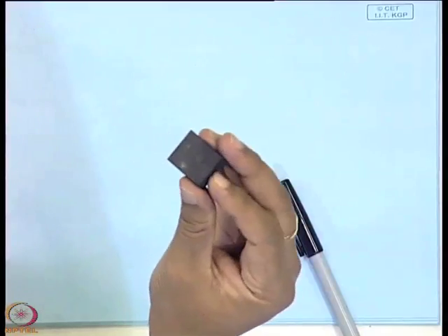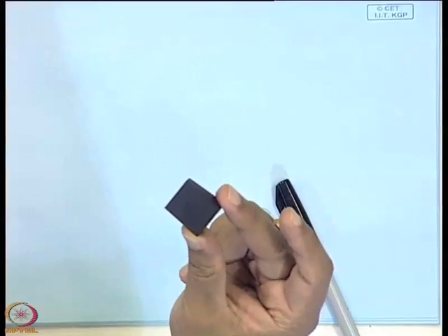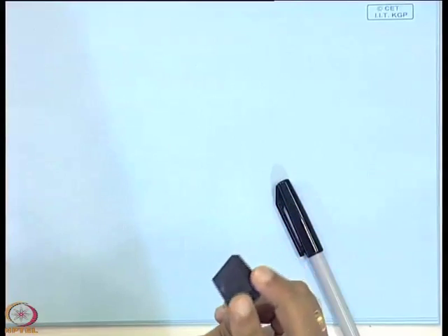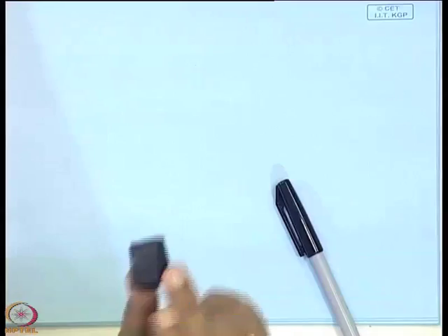If you see the construction of this type of reactor, this is the susceptor. This is a graphite block, this is basically a susceptor. This susceptor is placed inside the reactor. On the susceptor, the substrate is kept. You see the shape of the susceptor; on that susceptor you place the substrate. Now, what is the dimension of this susceptor? The dimension of this susceptor is basically 2 centimeter by 2 centimeter.